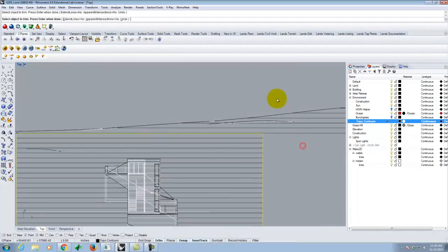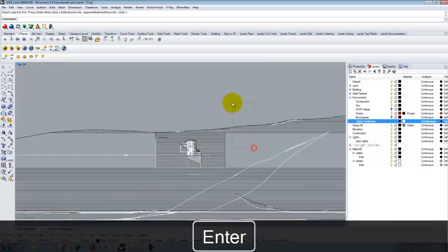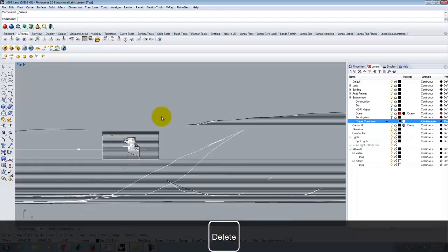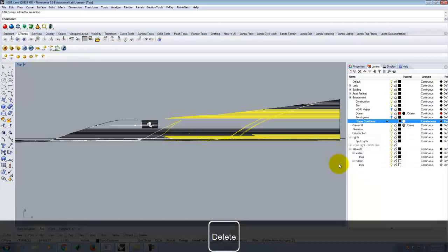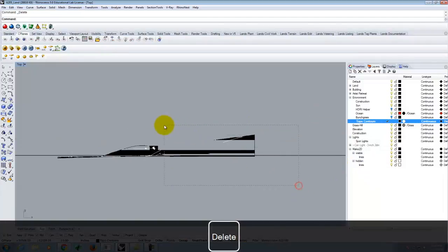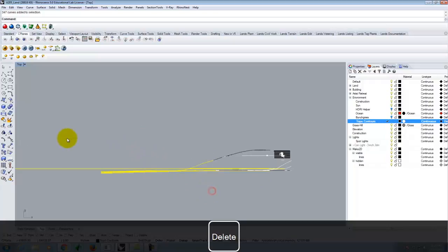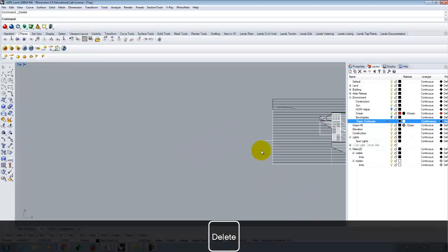And anything that's up above. Yeah, okay. Sounds good. I'll hit enter to finish, and then we'll delete the rest of these pieces because this is all information that I don't need. That's the risk when you select all when you do the Make 2D. You get way more information than you actually need.